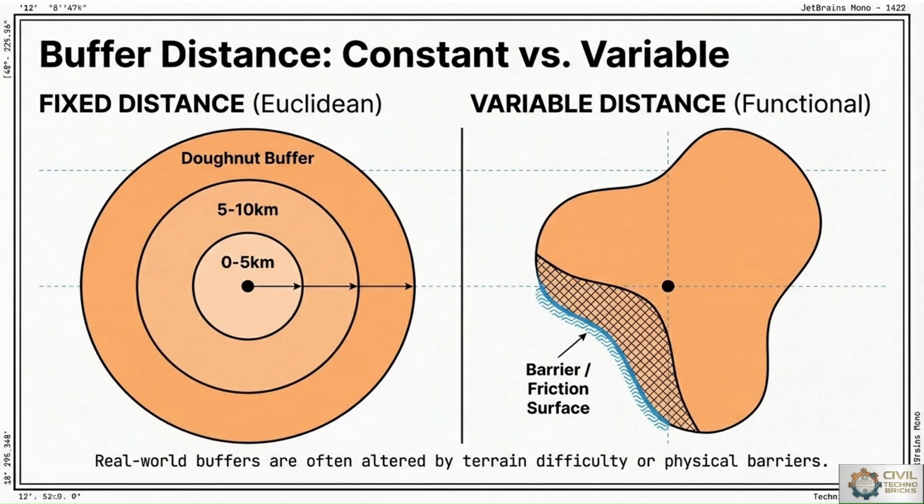With the barrier or any friction surface shown in image 2, we can mark the distance functionally, and that distance may be used for real world applications. The second image is most important for hilly regions or for applications of road construction and railway alignments, but in urban mapping and planning we prefer the constant buffer distance. A constant buffer applies the same distance to every feature in a layer, such as a uniform noise buffer around a highway. In a variable buffer, a specific attribute defines the distance.